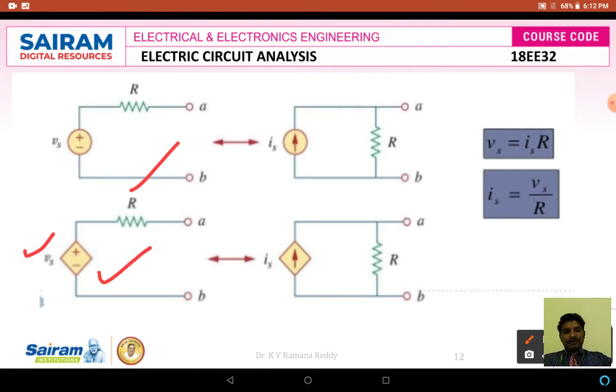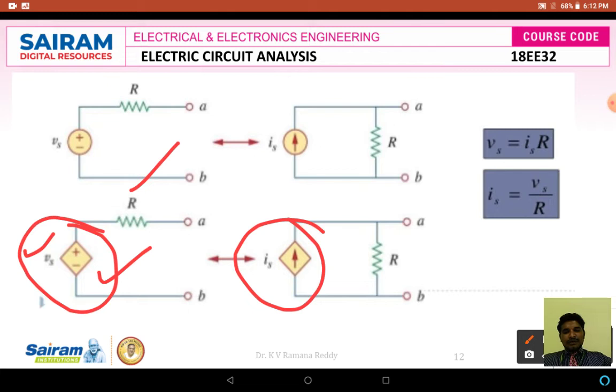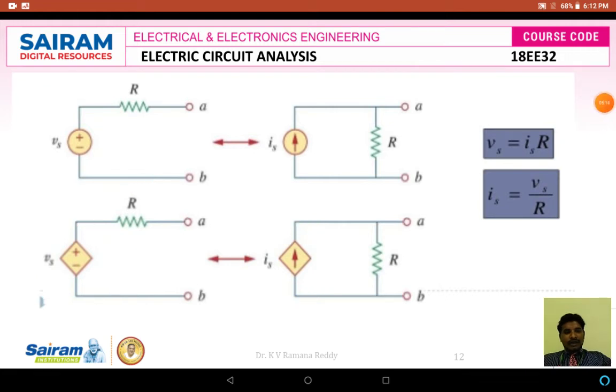Here I am going to convert this dependent voltage source into a dependent current source. How is it possible to convert the dependent voltage source into a dependent current source? It is possible with the following formula, as we can convert the available dependent voltage source into a current source. We know the formula Is is equal to Vs by R. Here where is Vs?